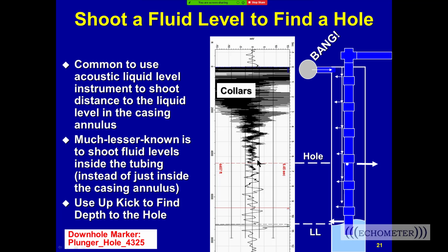I have examples of tubing where the hole was an 1/8 inch in diameter and it showed up. So typically you'll see a hole, and if it's a quiet well and you've got some pressure in the well, then I'd say you'd see tiny holes, maybe even 1/16 of an inch in diameter, not very big. I think the answer would be yes in most cases, but if the hole is a seep through the threads, you won't see it.